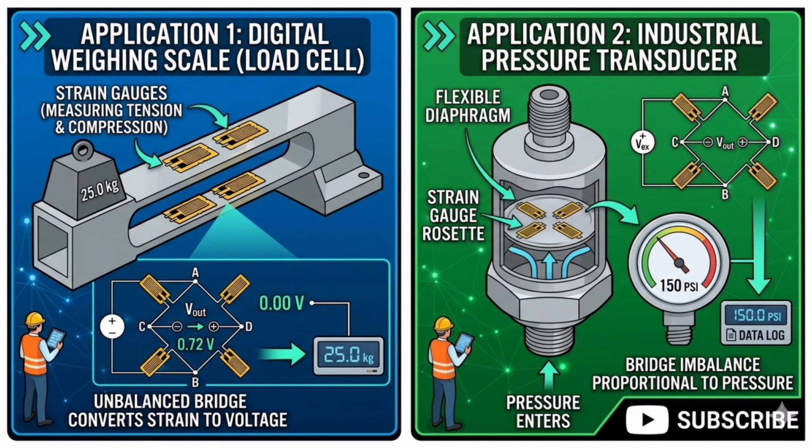So suppose I'm putting any weight over the machine, what is happening? It causes change in the strain, or deforms the resistors, and deviates the circuit from its balanced condition. It is detected electrically within the device, which you can convert into the weight of the body, right?